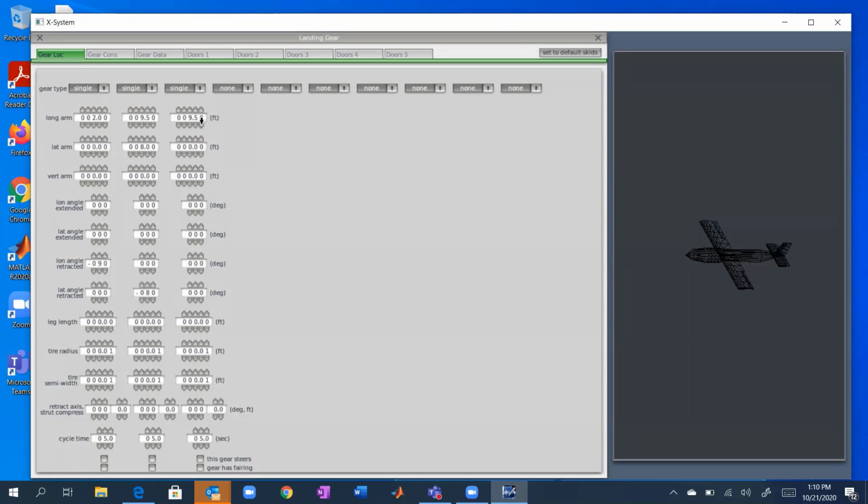And then this one is still located aft, but it's going to be 8 feet on the left side. So it's -8, and it's going to retract the opposite direction. And now I'm wondering why I have 90 on one of those and 80 on the other. I think they both should be 80. All right, the handout shows a 90 where I just put in the 80. And that's a matter of, I think I looked at the airplane and saw whether it went up in the wing and looked nice or not.